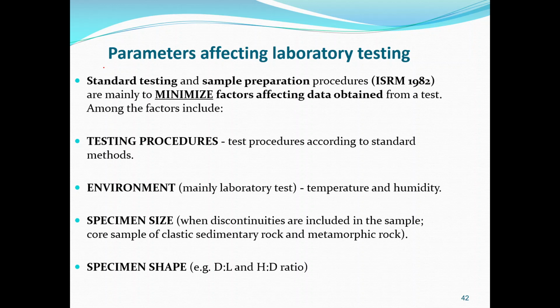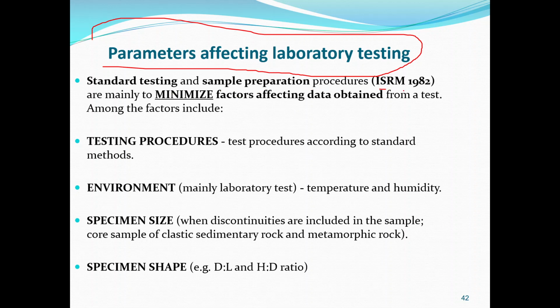Now we discuss the parameters affecting the laboratory testing results. Standard testing and sample preparation must follow the ISRM standard, and this is to minimize the factors affecting our results, meaning that everybody has a similar procedure. Then the environment, so look at the temperature and humidity. The specimen size must be specified as recommended.